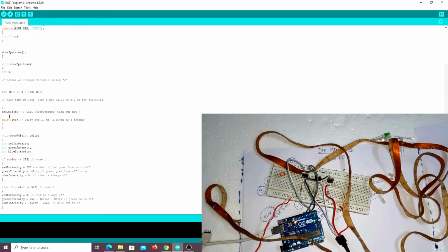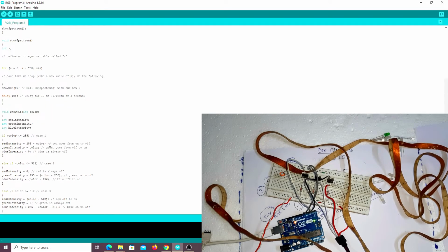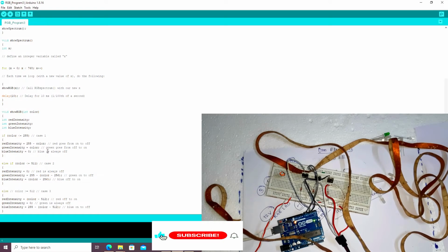It will give you a 50-50 mix of blue and red, resulting in a purple color. If you count up from 0 to 767 and pass that number to this function, the LED will smoothly fade between all the colors, because it starts and ends on pure red, so you can start over at 0 without any break in the spectrum.